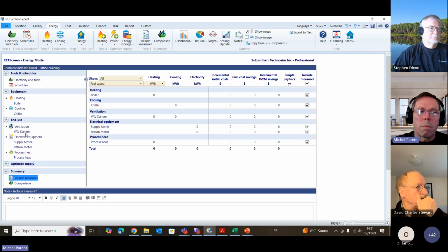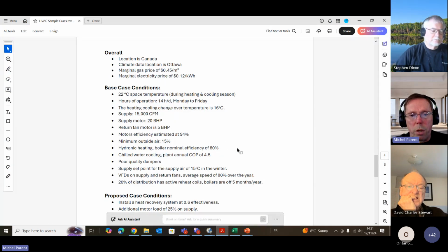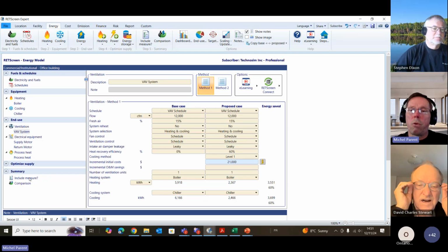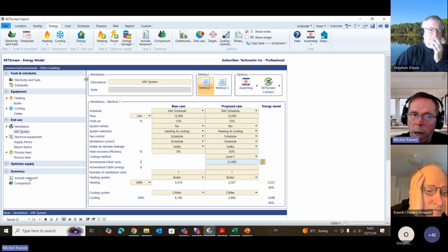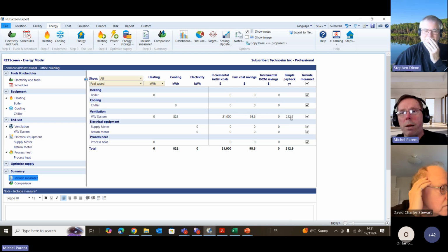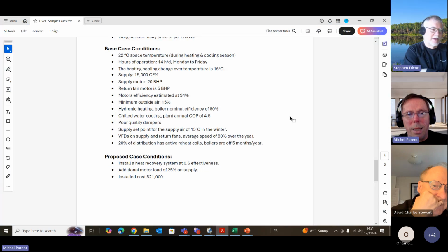And as before, I'm going to go here. And now you guys are not going to be surprised. I'm going to put 60% effectiveness. And it's probably the same price, $21,000. It's the same size system. Yep. And I'm going to go back into my include measure before I even put the correction for the fan power. And just like before, actually, the payback is 10 years better than before. So you only have to wait 212 years rather than 222 years to get your money back on this measure. And it'll only get worse if we add in the increase in load on the supply and return fan.